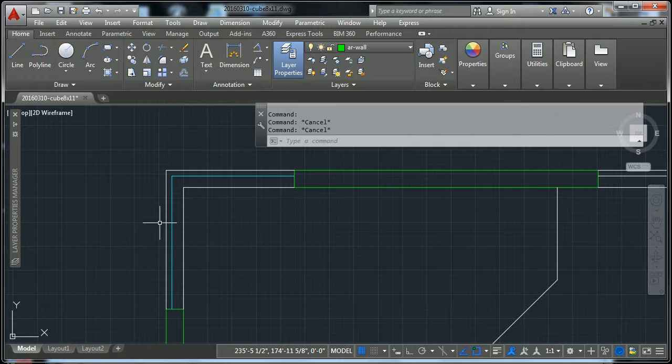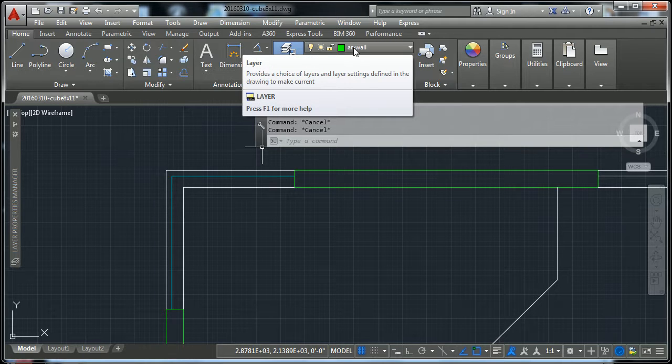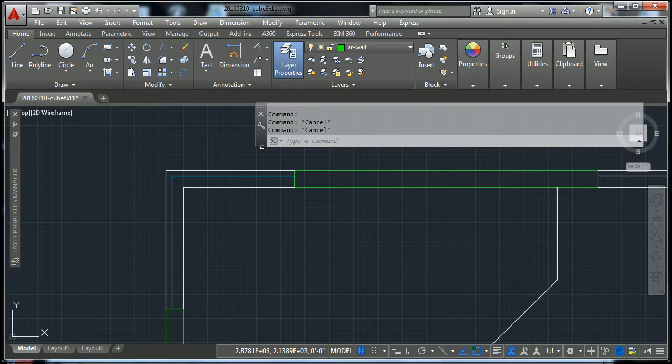So if you're looking at that clerestory window right there, if you put the floor plan line or cut plane line right at the middle of the glass, you'll see the top of the wall, right? So this will represent the top of the wall, so we'll have to make another layer that represents the top of the wall. So we might say AR sill or something like that.